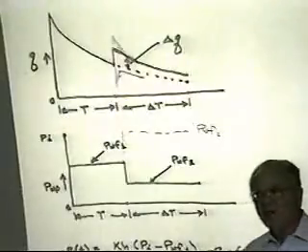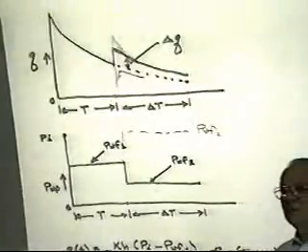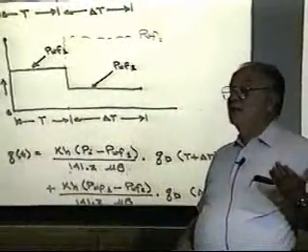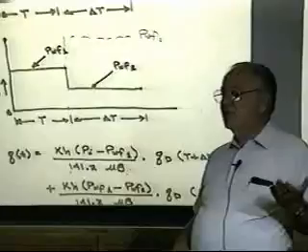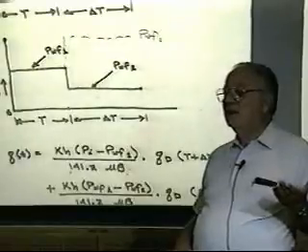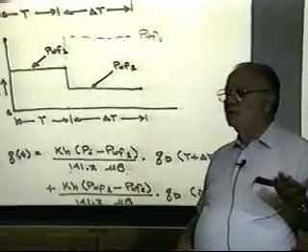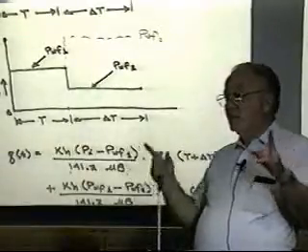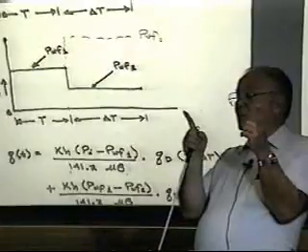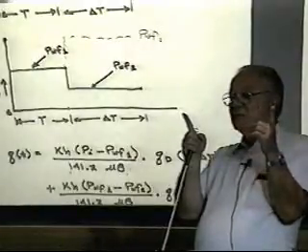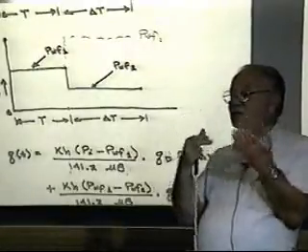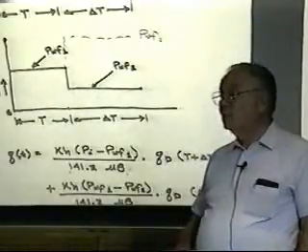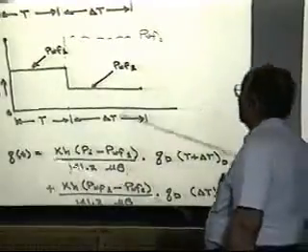Well, the people that are attempting to go into the pseudo time say, well, I can get more rigorous superposition into my problem if I introduce a pseudo time, but if you go back and relook at the QD TD for the ARPS equation, there's a long period there, whether it's exponential or a b equals 1, where it basically overlays. That's normally the interval of superposition you're interested in anyway. Okay, so it really doesn't make that much difference.